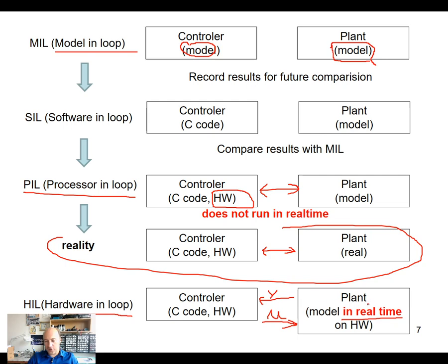Now in case of a slow thermal system, it's not difficult. If this plant requires a control algorithm to act every 5 minutes, then the controller in hardware has enough time to do it. So it's all about the ratio between the speed of the plant and the speed of the controller. On the other hand, there are systems where this might be very difficult.